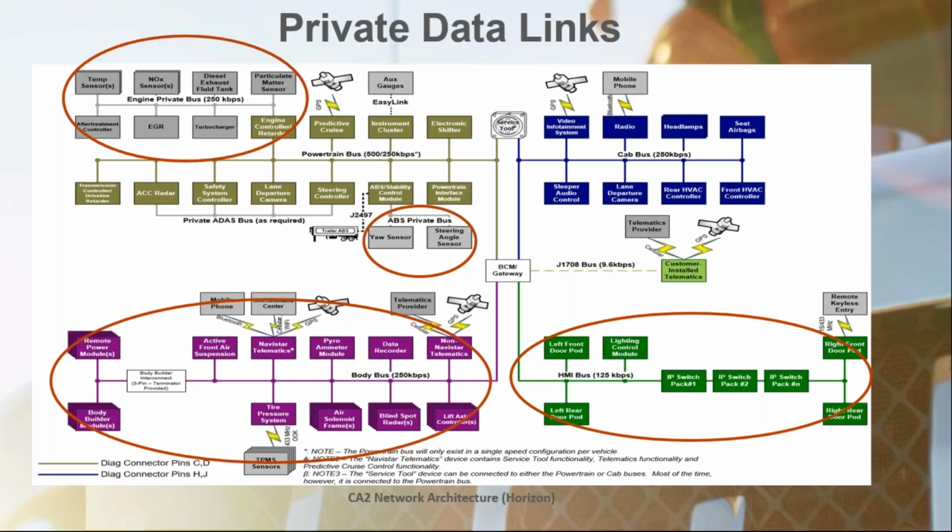Then you see the zigzags for some of the telematics, some of the wireless GPS type stuff. There's a lot of options there for multiple things going on. Gateway modules, there's a couple of them on our trucks. The ECM or engine control module is one. It interfaces with the after treatment system, private CAN. Any information on that that is needed can be sent down into our Datalink connector for fault recording or retrieval, and that's sent through the ECM.